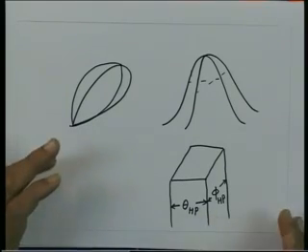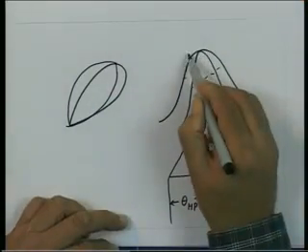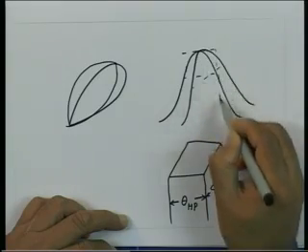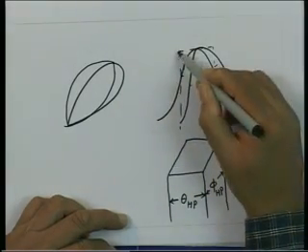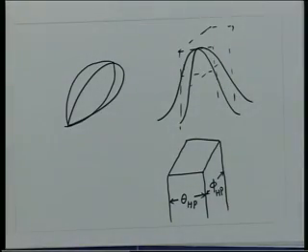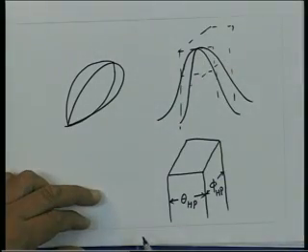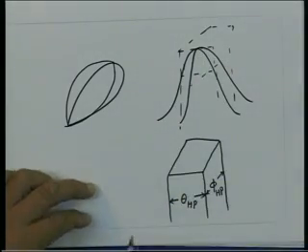So, we can make an approximation that the power is just confined to this region of half power beam width, and beyond that the power is practically 0. So, the integral which I require for E square, essentially I can say is approximated by a box. And within this, since it is a normalized radiation pattern, this amplitude is 1, so that means the height of this box is unity.